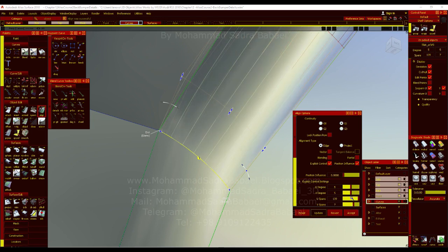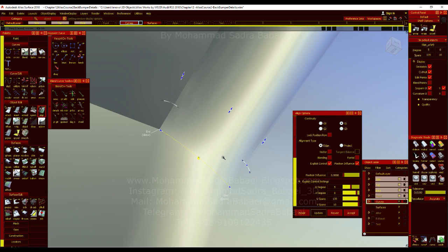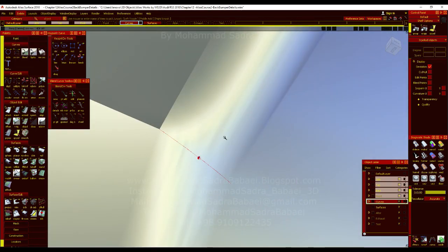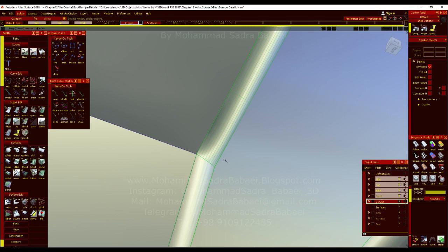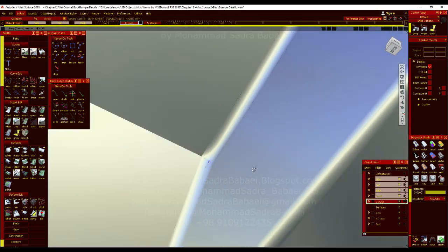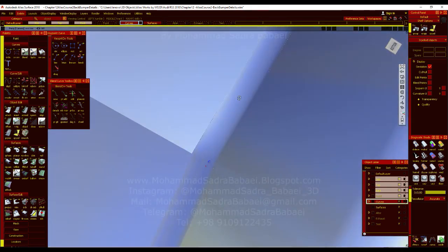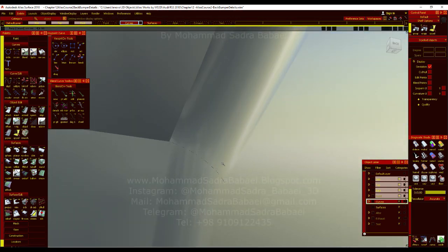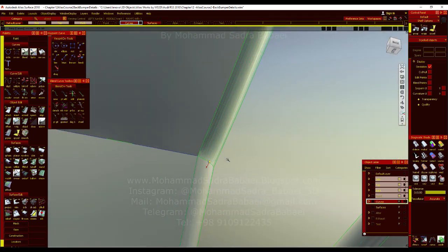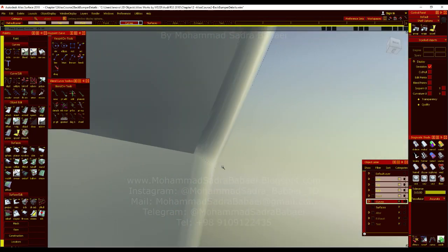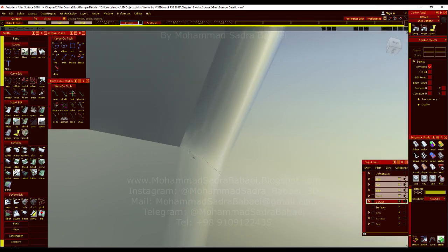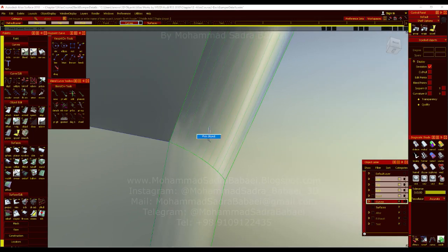So it's not going to create because I told you I should fillet that main surface. You know, because they are completing positionally. So it's not matched. As you see, it's not matched very good, because the main surface doesn't have any fillet. So we should add a fillet there and then continue working on this section. I just wanted to show you, you can't use the align tool if you don't use the fillet tool for the main surface.